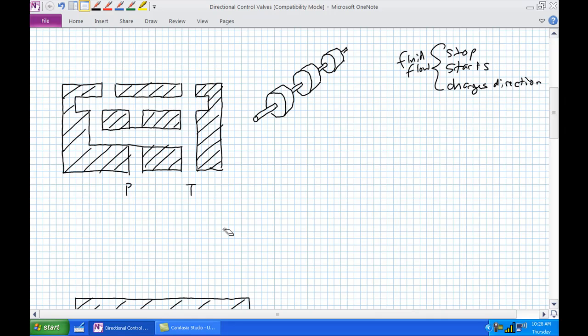So that's the valve housing into which a spool fits. The spool fits in this passageway right here, which is cylindrical in nature. And you've got these things on it called lands, and the next one is valleys. A land is sized big enough so it's going to bridge the gap, with enough tolerance and clearance that it can move, but it's going to seal off one side from the next.